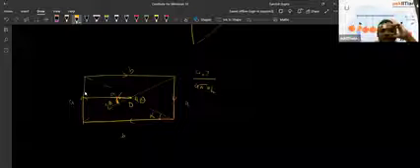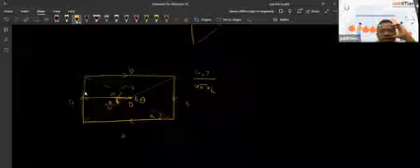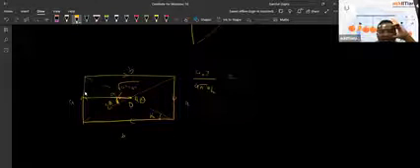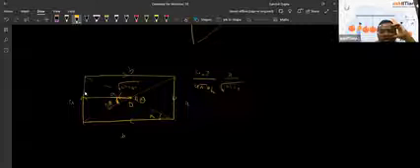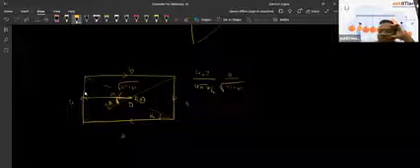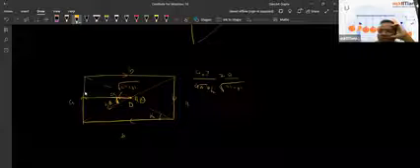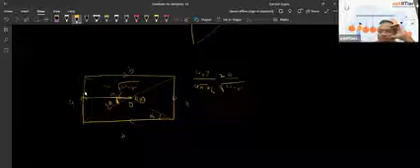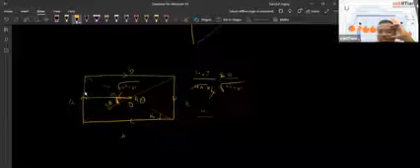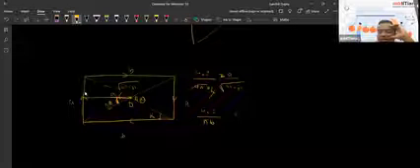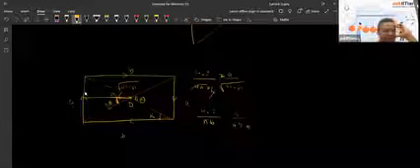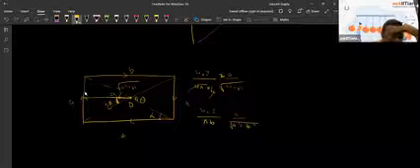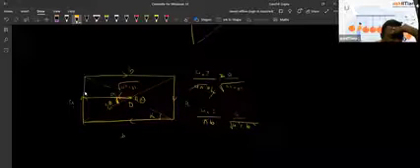See, so sin alpha is, this is the diagonal, square root of a square plus b square. So sin alpha is a divided by the square root of a square plus b square. Sin beta is also the same, so it will be 2 here. So 2 and 2 and 4 get cancelled out. It is coming out mu naught I divided by pi into b, into a divided by the square root of a square plus b square. This much is coming.